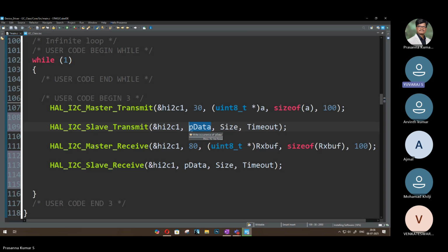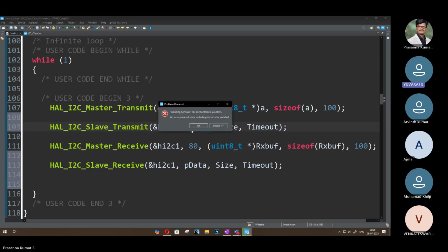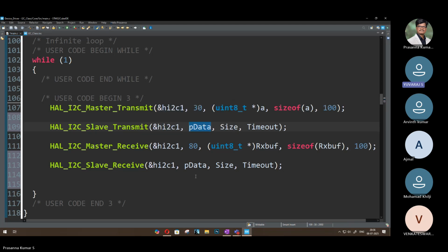And one more thing, for example, we have different parameters of data, like voltage, current, and state of health. All three parameters will be under this uint8_t star a, like that. There is only one data we are sending here. See, any data which is transferring in I2C or SPI or UART is transferring bit by bit.